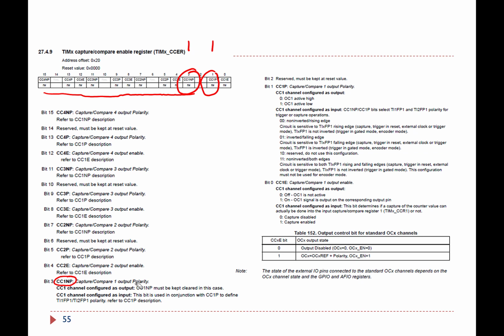It says CC1 channel configured as output, and it says CC1NP must be cleared in this case, and it says CC1 channel configured as input.